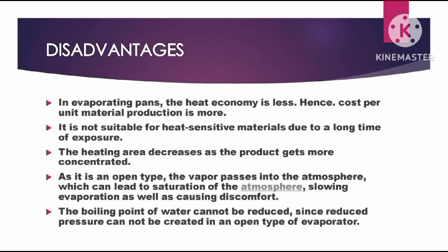Now talking about the disadvantages or demerits, the most important is the less heat economy, which means that the cost per unit material production is more. Secondly, it is not suitable for heat sensitive materials due to long time of exposure, and these long exposures can lead to their dissolution and deposition, hence not yielding the required product. The heating area decreases as the product gets more and more concentrated.